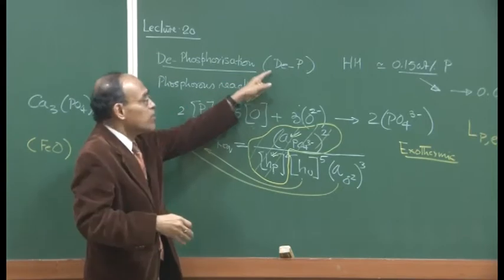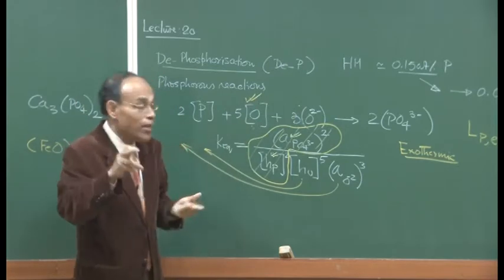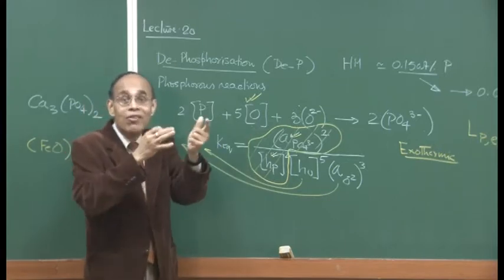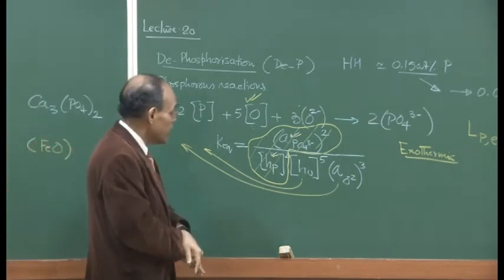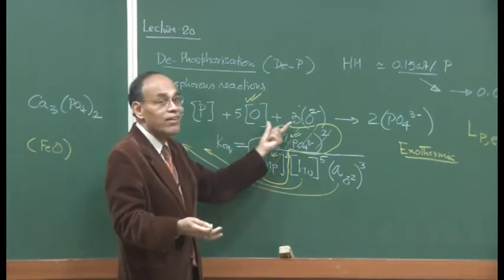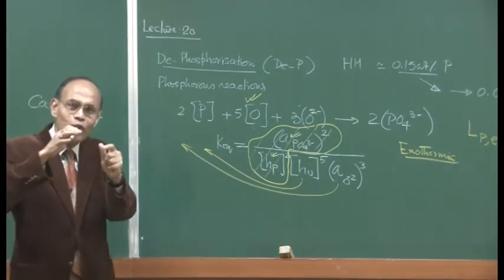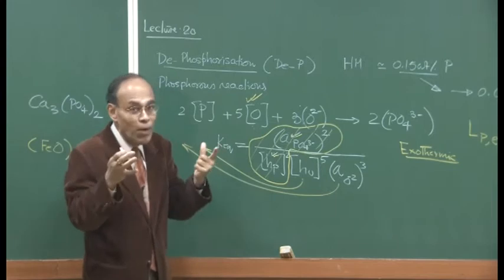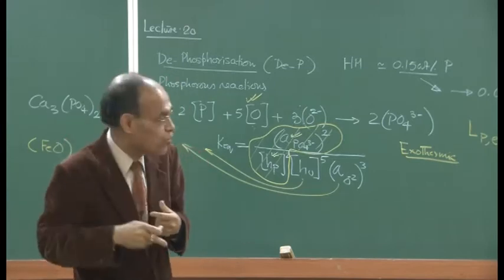And if you now compare desulfurization with dephosphorization, you will see that in desulfurization, as we said, we require a basic slag but we also require a reducing environment. So, the objectives are quite opposite as far as desulfurization and dephosphorization are concerned, and that is why I have been repeatedly saying that sulfur removal is facilitated in the blast furnace. On the other hand, phosphorus removal is facilitated in steel making. Also, we must understand that in the blast furnace we are constrained about using a very high basicity. On the other hand, in steel making we have no problem, because we have extra heat generated from the oxidation of carbon to carbon monoxide and the oxidation of silicon to silicon dioxide.